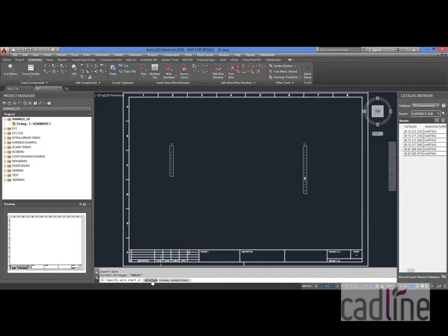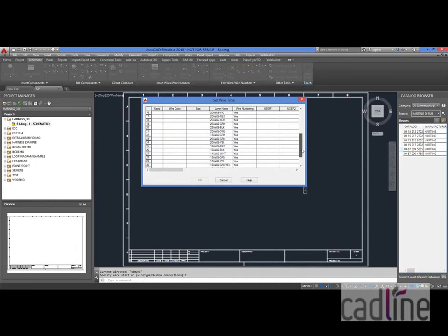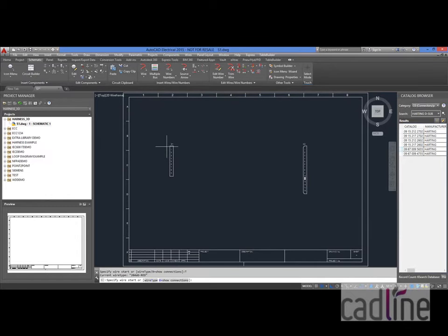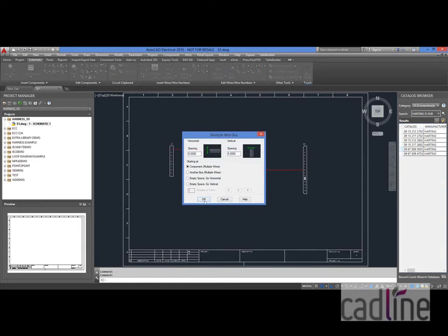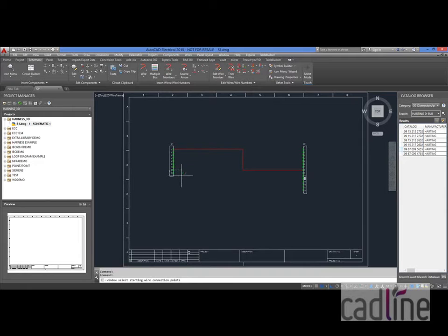When we're drawing wires, we can choose what wire type we want to use. And you can draw from connections, showing the little X's. And it automatically cuts back the wire when it connects up to the pin. We can also draw from the component, selecting round a couple of connections. And then we can flip the connections if you wish and continue, maybe even flipping them again into the required pin connections.